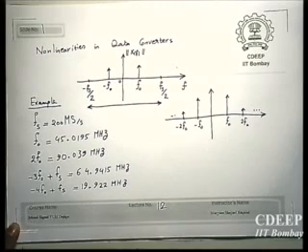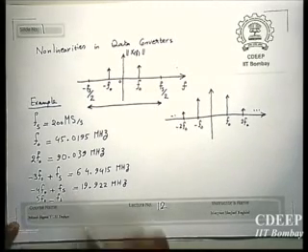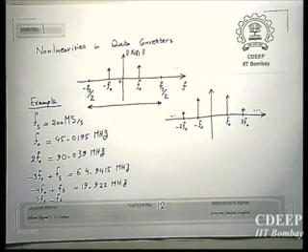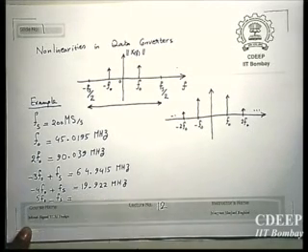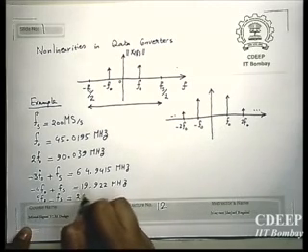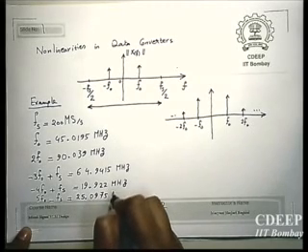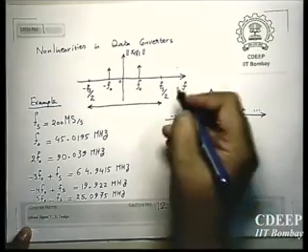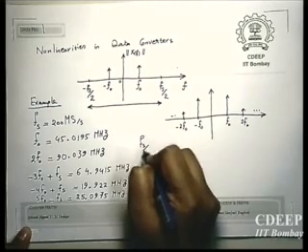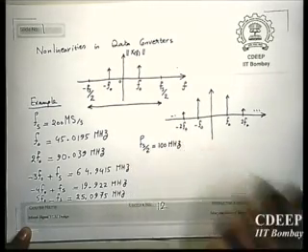Then you can have from the other side, for example, 5f0 minus fs. Now these are positive harmonics shifted to left. That tail also will come to your band. So therefore you will have 5f0 minus fs, which will be 25.0975 megahertz. All of them are less than, as eventually your fs by 2 here, 100 megahertz. All of them are less than 100 megahertz.